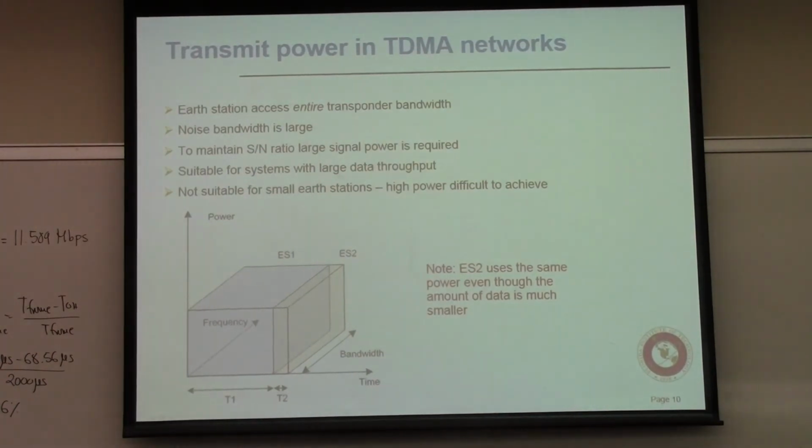Just to summarize, we have a synchronization of the incoming signal that's done at the receiver, and then synchronization to the network, which is access synchronization that's done at the transmitter. The transmitter needs to be synchronized to the frame structure of the TDMA so that it makes sure that it doesn't overstep on all the other transmissions that are happening in the network.